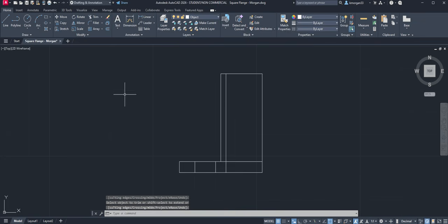Then we will get into teaching you how to use erase and trim. Sometimes you have to click it 2 times to get the little square cursor so that you're in the erase mode. And of course we want to erase this, see that? And of course you will have to end by hitting the enter key.